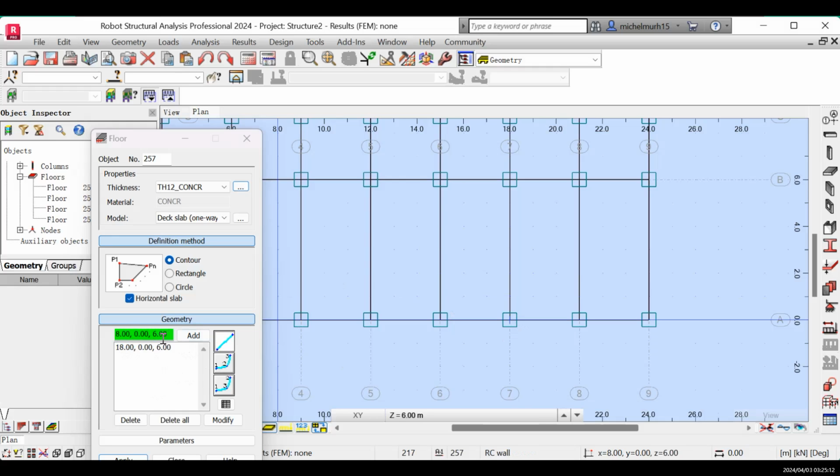My objective is to create a slab where the thickness of the slab is half. The thickness of the slab is 1, so I'm going to take 0.5. My Y direction should be 0.5. If it's hard for you to pick 0.5 here, you can just modify it here.